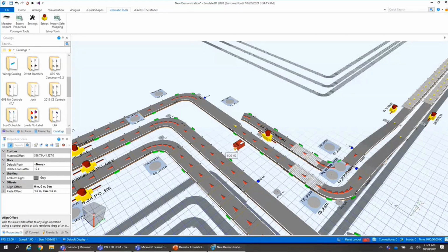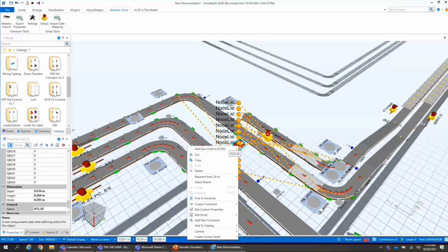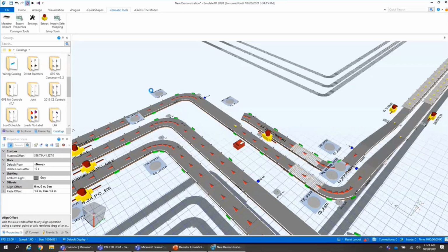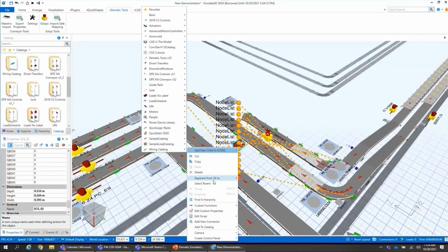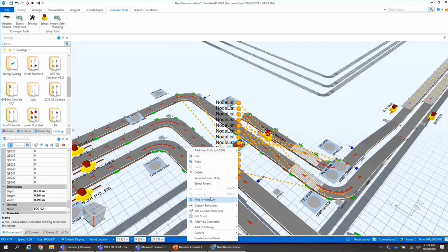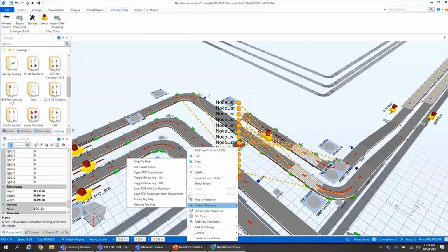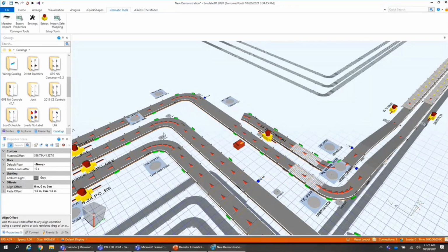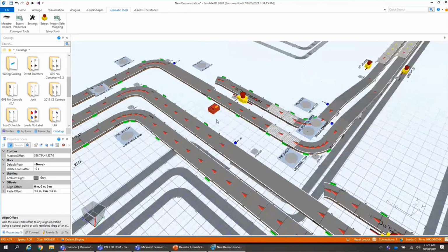So that's really helped, having the same terminology in the model as what we're going to see on site. And so the last thing that we did was this gateway here. On site, we have a socket that we use, a configuration socket, and in the emulation as well, I have the same socket connection. So instead of opening sockets for all these devices, sometimes we'll have 20 or 30 gateways in there that want to open all the sockets in one area.